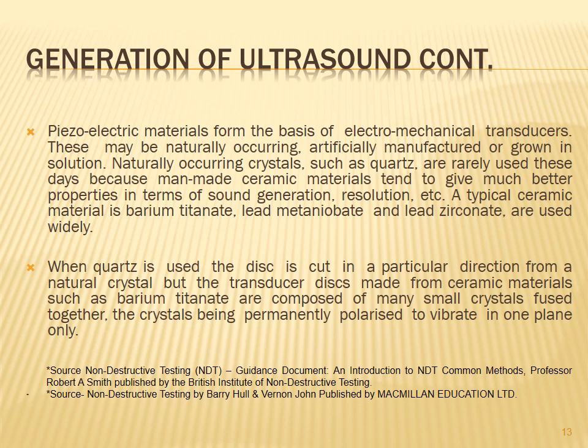When quartz is used, the disk is cut in a particular direction from a natural crystal. But a transducer disk made from ceramic material such as barium titanate is composed of many small crystals fused together, the crystals being permanently polarized to vibrate in one plane.